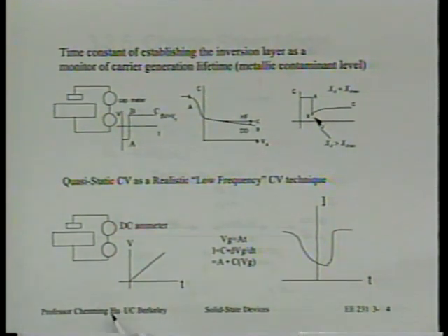All right. If Vg is linearly changing with time, let's call that At, where A is just the ramp rate, right? Vg is equal to A times t. If so, do you agree a current will be flowing through this capacitor? Right? Because you have a dV/dt. Current is equal to C times dV/dt, therefore it is equal to A times C. Do you follow what I'm saying? So if we can measure that current, since we know our ramp rate A, then we will get C.